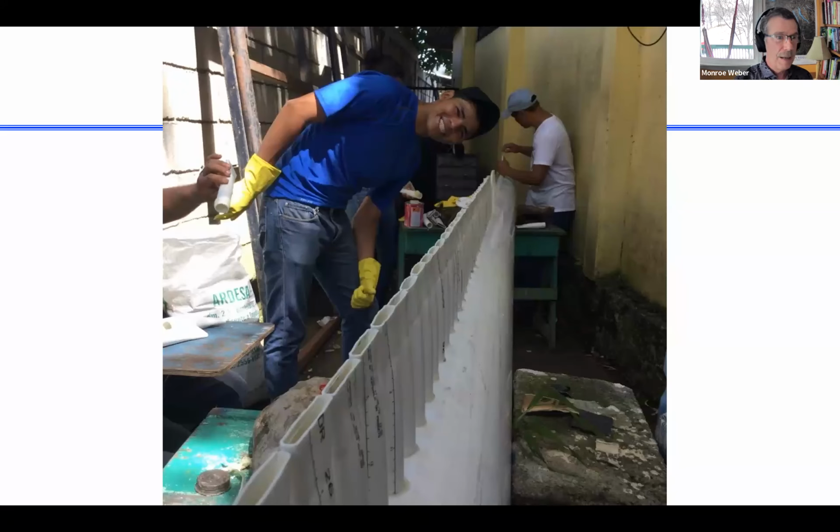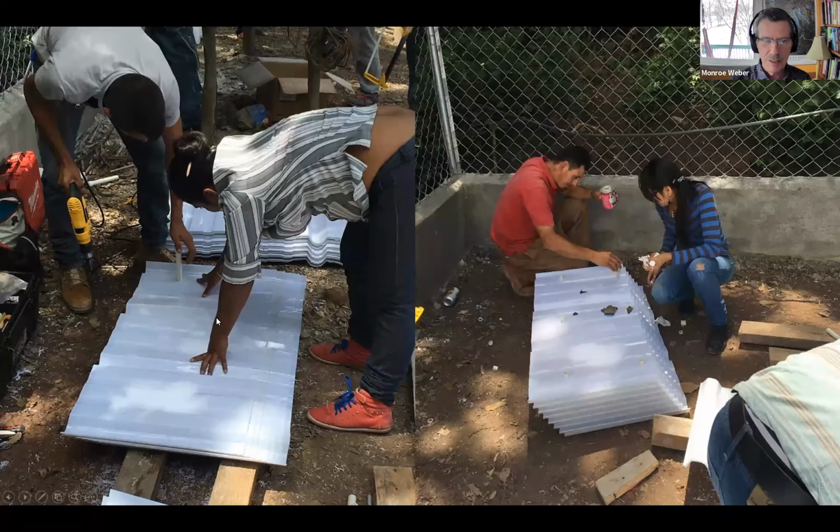This is the fabricated inlet manifold upside down with the diffusers pointed up. Those are the diffusers that will be pointed down and will be delivering flocculated water into the very bottom of the sedimentation tank. And those diffusers are made in a very cool process. I forget if I have any images of that, but they're made by heating up the PVC in hot vegetable oil on a little stove. It just needs to go to a temperature a little bit above boiling, just a little bit above 100 C, and that's enough to soften the PVC so you can mold it.